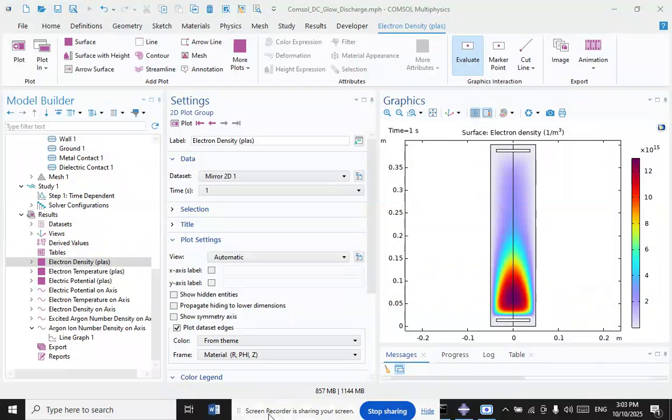The use of this radio frequency will establish a negative DC bias voltage on the sample surface. The DC bias is the result of an alternating current waveform that is centered about a negative potential. As such, it more or less represents the average potential residing on the sample surface. Radio frequency has the ability to appear to follow through insulators and non-conductive materials.